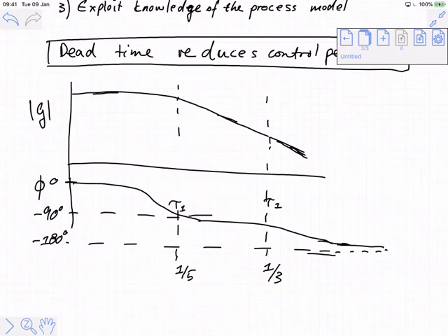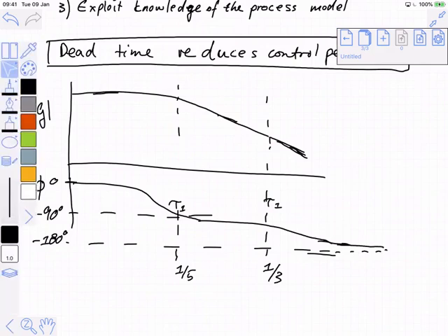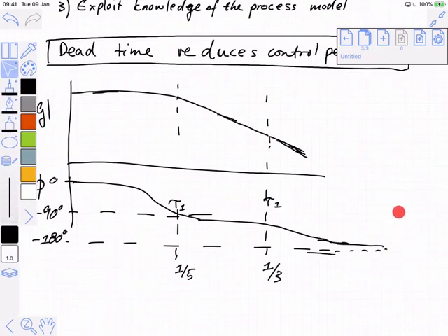What's cool about the second order system just by itself is we can see that we will never actually reach that frequency. There is no frequency at which we are crossing over 180 degrees, right? And the magnitude looks like it just goes all the way down. So even if we could imagine touching the minus 180 line somewhere very far that way, that equivalent gain would be minuscule. It would be very, very small. And so we've kind of guaranteed stability for any kind of gain that we can think of.